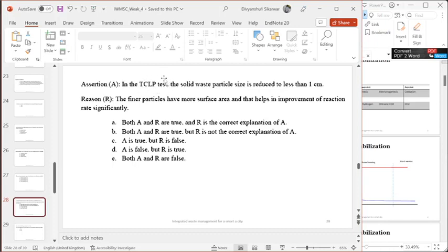The idea is not to be on the side of underestimation, because if we put in landfill something which leaches more of certain chemicals or compounds, it goes to groundwater, which is not right. So TCLP basically overestimates the amount of leaching.